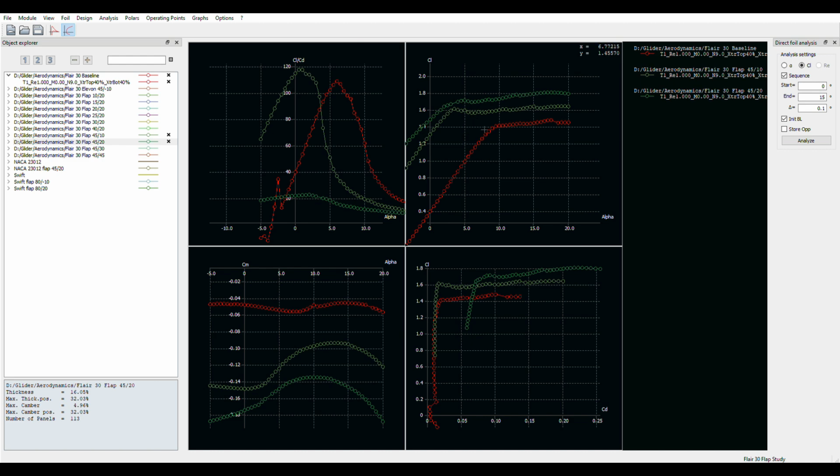So at this point, if I were the pilot on this aircraft and I'd done that, I think I'm in a mushing stall. If it were a powered aircraft, they'd call it on the backside of the power curve. You've got to get the nose down, but how do you do that? I don't have enough power. Well, in a glider, you would. You just shove the elevons down, and you might get the nose back down and get flying again. But you've literally jumped from a flying configuration to a stalled configuration instantaneously. And that's because that darn flap is hinged so far forward, such a big percentage of chord.